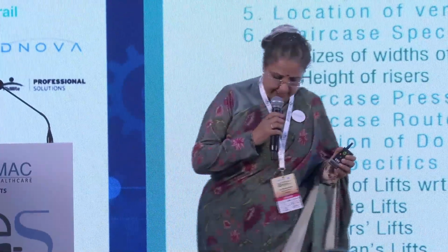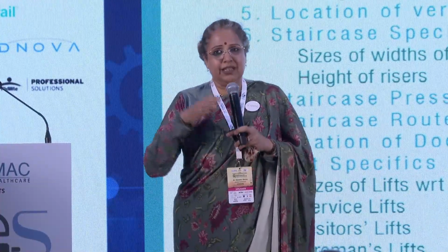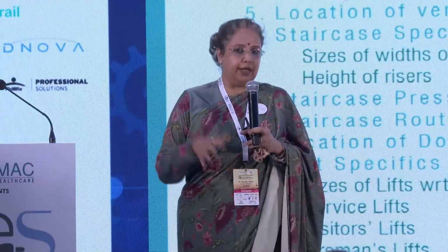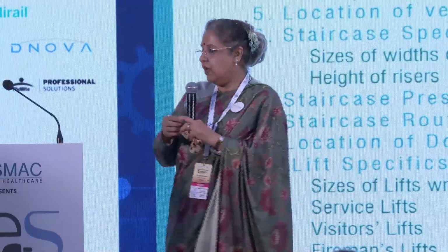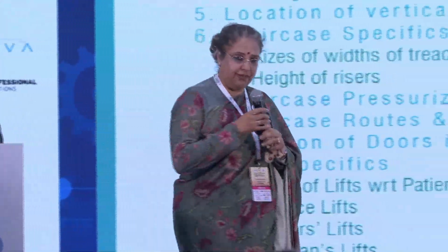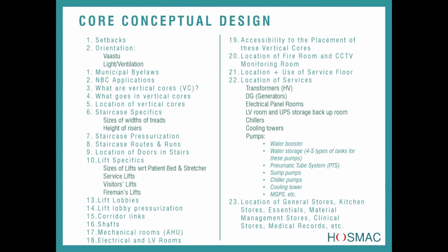Staircase specifics, then location of doors, lift specifics, which are the different kinds of elevators which come in a hospital. Now, this is of great value when we design hospitals, because there are different sizes, different cores, different places where people enter, visitors enter, doctors need to be segregated, there has to be a dirty and a clean core, etc. All these segregations bring in what we think puts together a hospital.